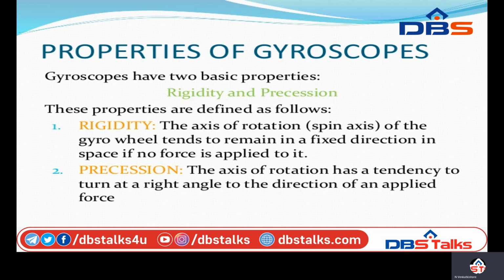Rigidity means the axis of rotation, that is the spinning axis of the gyro wheel, tends to remain in a fixed direction in space if no force is applied to it. Precession means the axis of rotation has a tendency to turn at a right angle to the direction of the applied force. That is what we get from the right-hand thumb rule also.